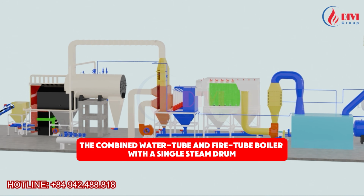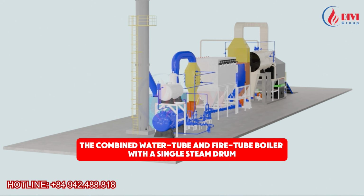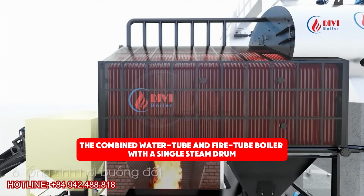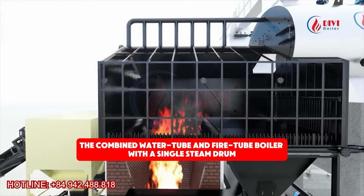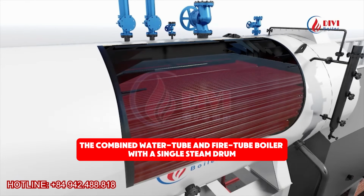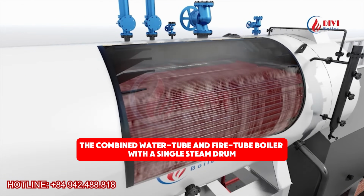First, the combined water tube and fire tube boiler with a single steam drum. This type of boiler has a radiant furnace surrounded by water tubes. The rear convection section uses fire tubes. In the furnace section, water flows inside the tubes, while the hot gases and flame flow around the outside. In the rear section, the hot flue gas flows inside the fire tubes, while water surrounds them on the outside. That's why this design is known as a combined water tube and fire tube boiler.